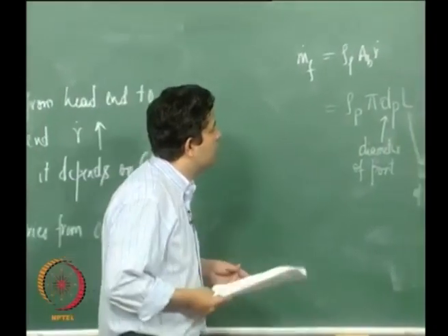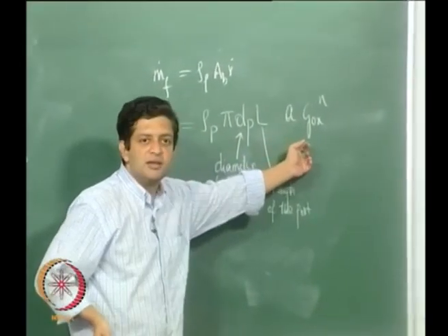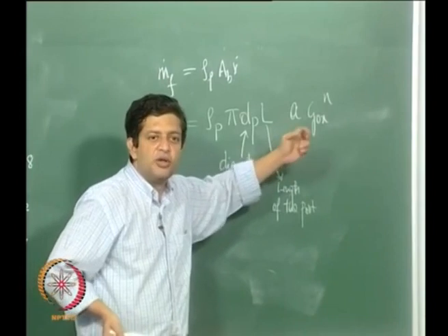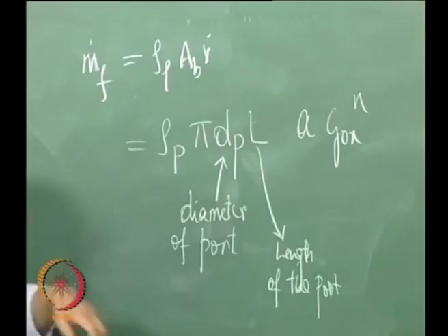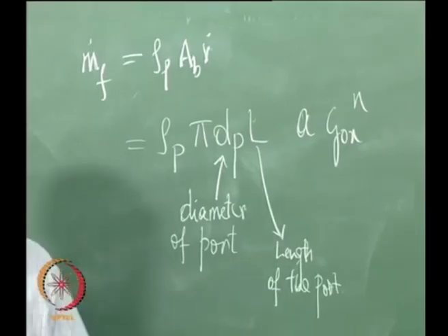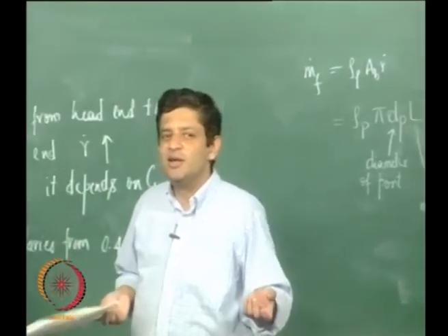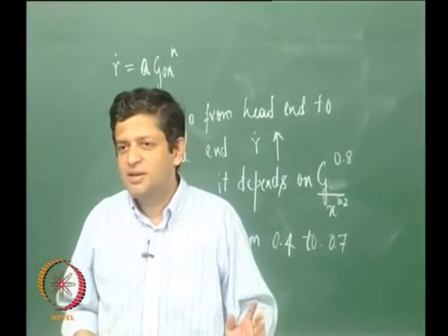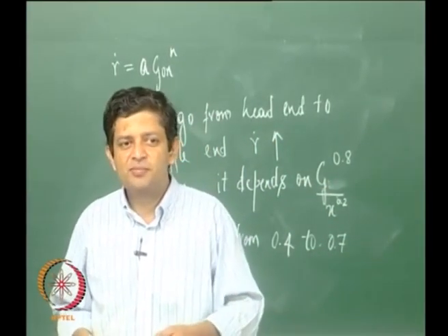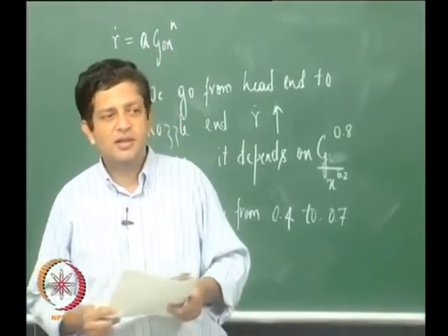Now let us determine what value of n will give us a constant fuel mass flow rate when you hold the oxidizer mass flow rate constant. If we can engineer such a hybrid, that is a very good situation, because you can operate it at a set specific impulse even though the diameters are changing.